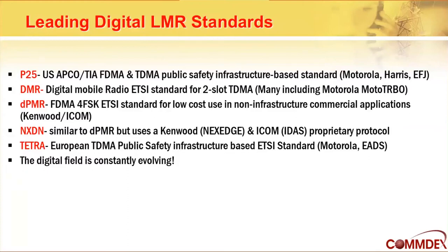DMR, which we're going to talk about, digital mobile radio, started life as a European standard from the European Telecommunication Standards Institute. Motorola took it and built their MOTOTRBO product line around it. There's lots of other manufacturers making it. That's a 2-slot TDMA technology that we're going to talk about.